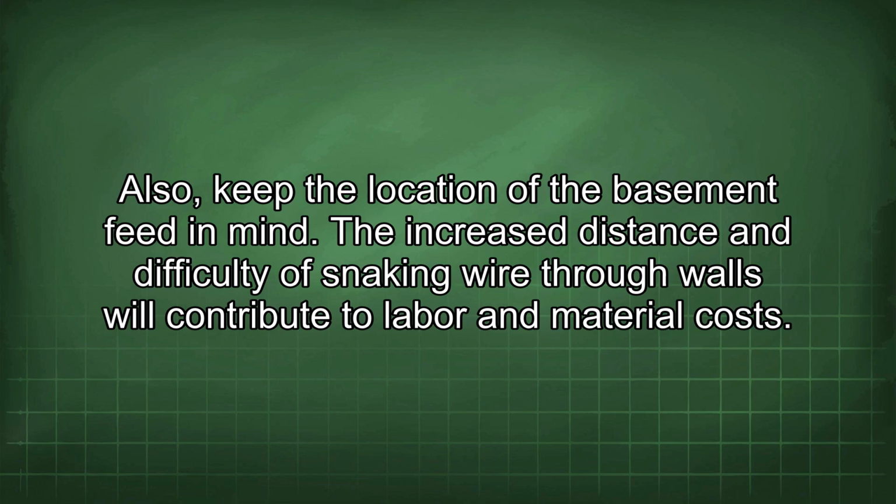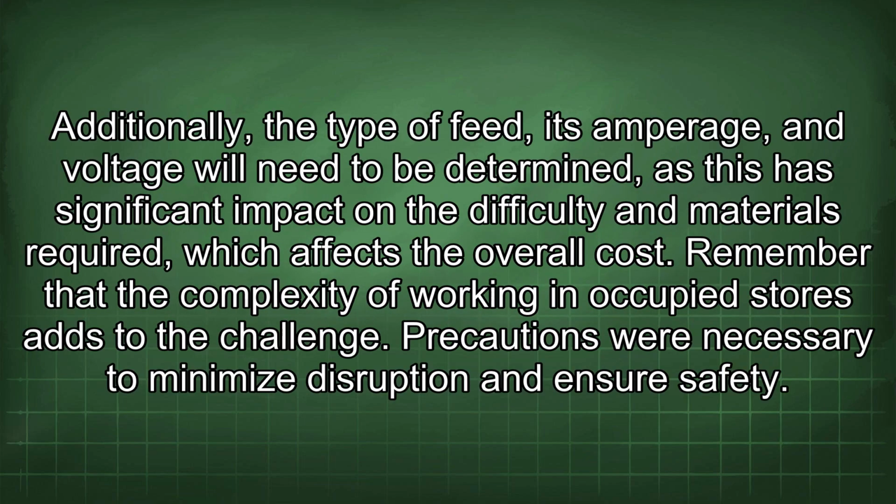Also, keep the location of the basement feed in mind. The increased distance and difficulty of snaking wire through walls will contribute to labor and material costs. Additionally, the type of feed, its amperage, and voltage will need to be determined, as this has significant impact on the difficulty and materials required, which affects the overall cost.